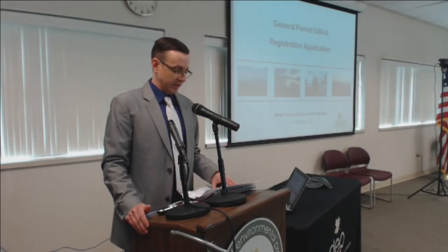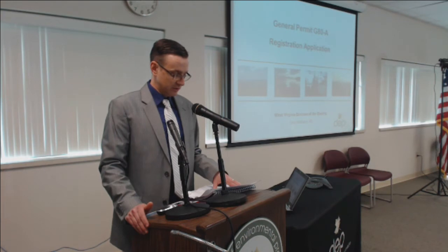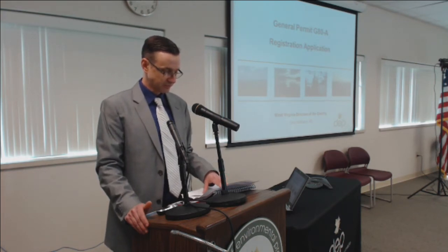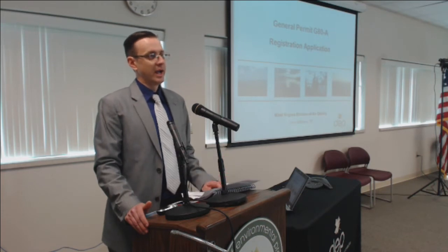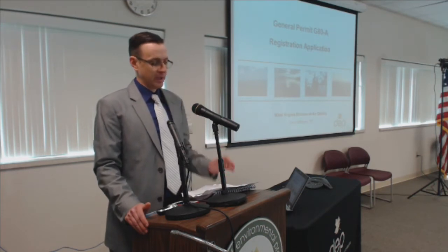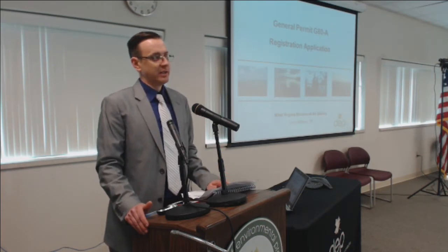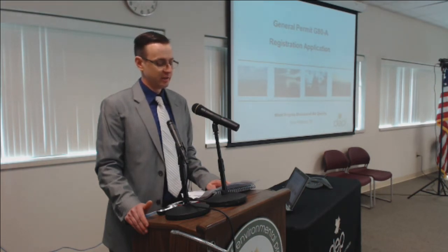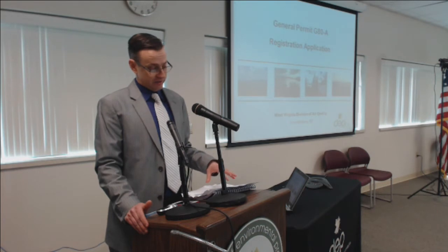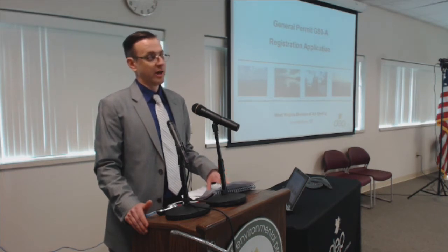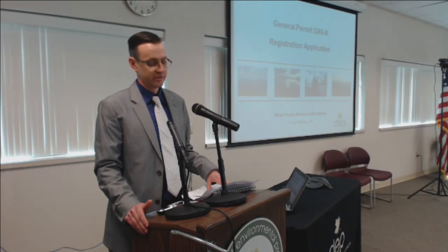A question. Can you go into detail on the requirements of the 6 tons per year tank rule? Looking back at what we went over earlier, Subpart 4.0 states that if your tank has emissions that are 6 tons or greater of VOC, then you're required to reduce the VOC emissions from those tanks by 95%.